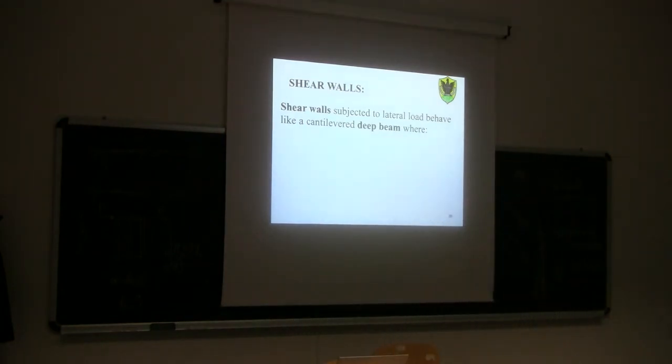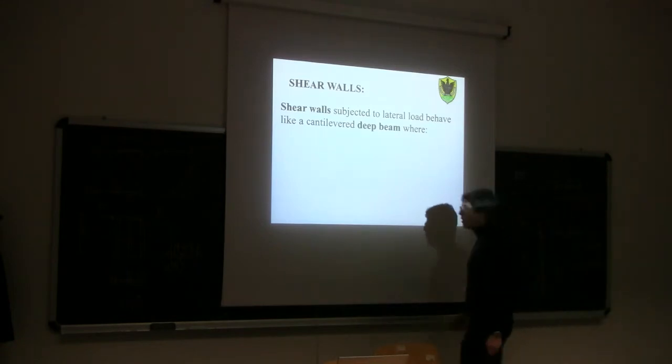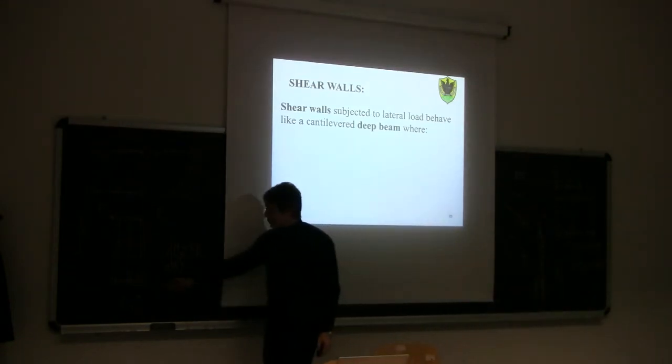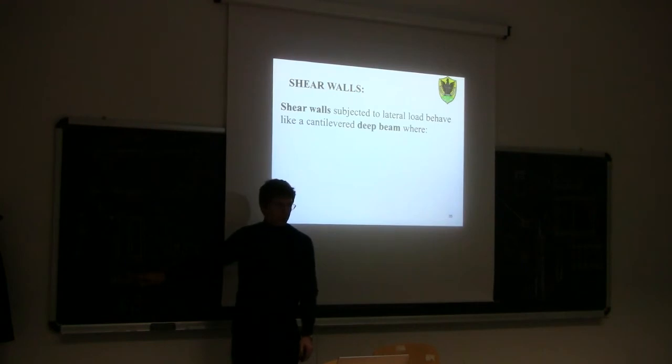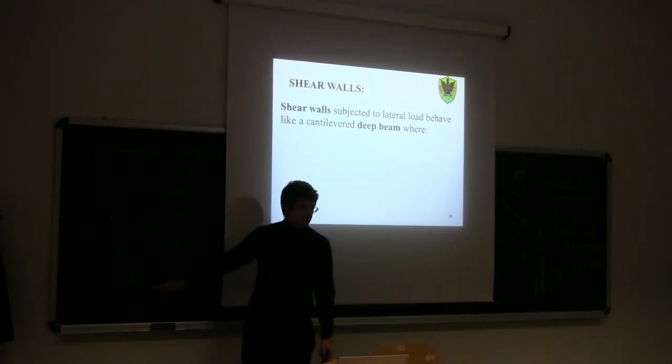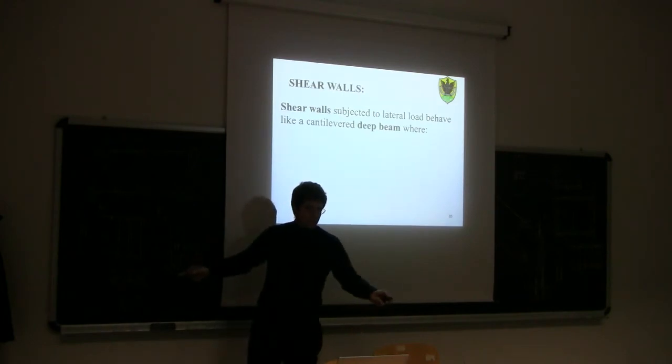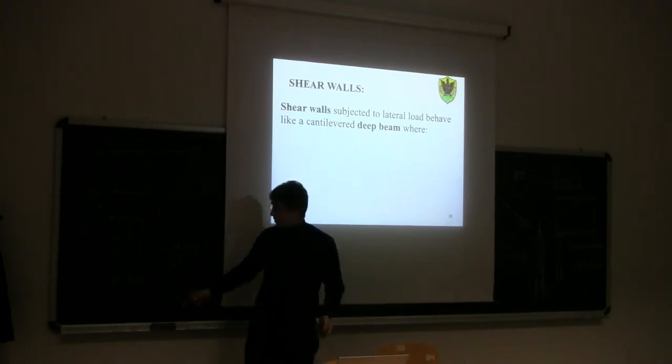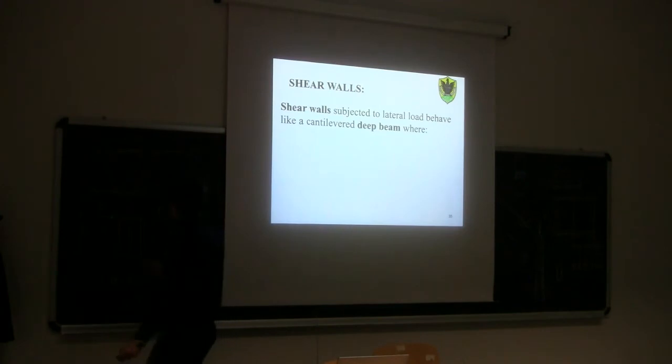Well, you could say, in terms of resistance to bending moment, I can ignore for sure this part here, because it's close to the neutral axis, and I can ignore also the web here, because the web doesn't take lots of stress in terms of bending moment. So I can transform this cross section into a cross section like this.